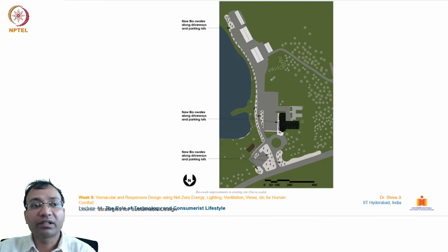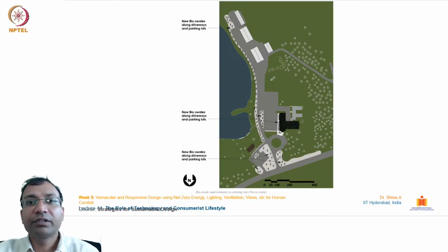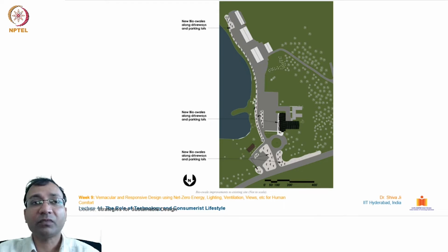Further, I have taken some examples over here for your understanding. So this one talks about the bioswales. Bioswales are man-made linear trenches which run for longer distances. They can help us increase the recharge of rainwater to the ground. So you see in this illustration how these bioswales are created along this paved movement place, this road, so that all the rainwater which falls on this surface can get accumulated in this bioswale, and this will help recharge the ground.